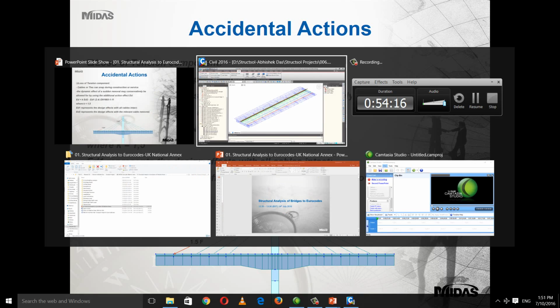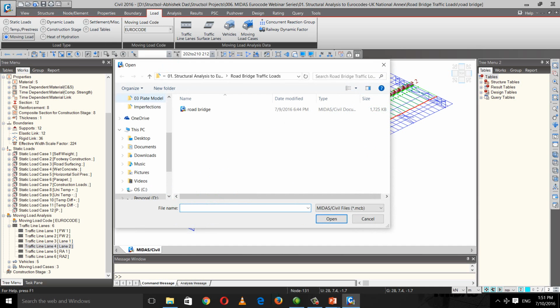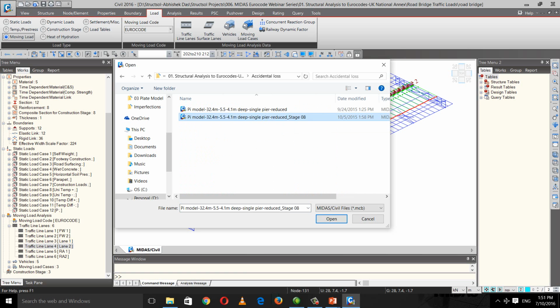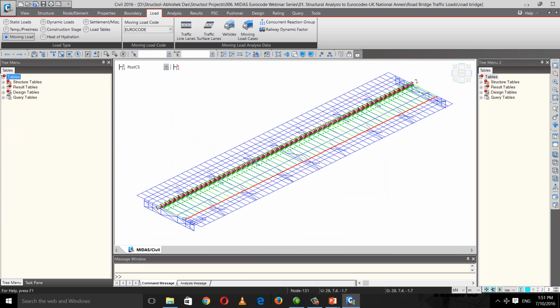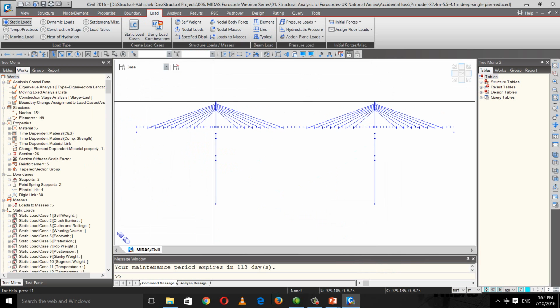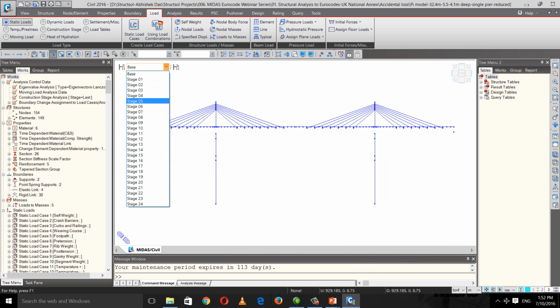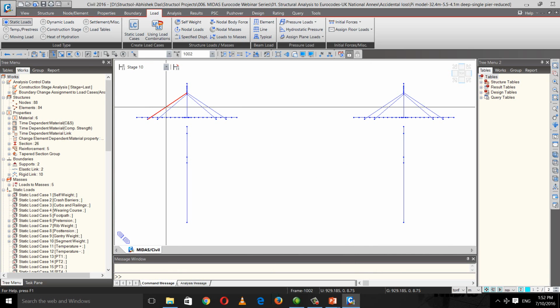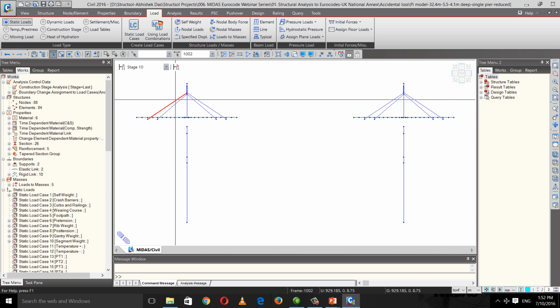So I'll just take an example of a simple cable bridge. Okay, so this is an extradosed bridge, so we can check for the hanger loss, cable loss scenario in one of the construction stages. So let's say this is the scenario. If we remove one particular cable, what we do in this check is simple, calculate the forces in the cables first in the normal state.